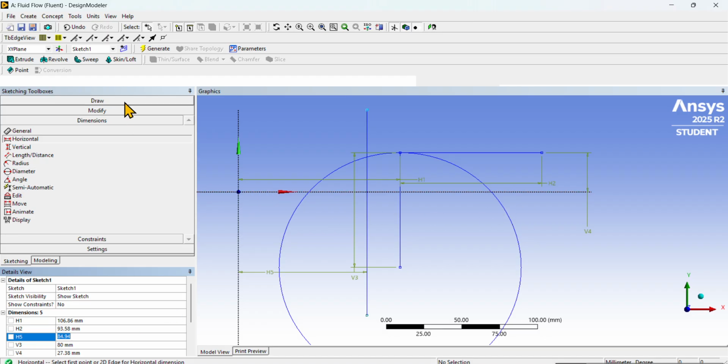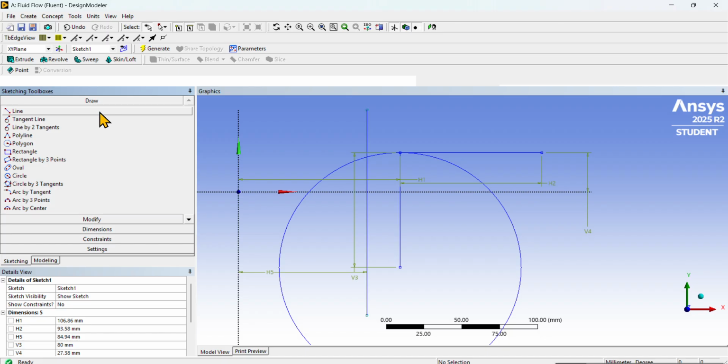So now we're going to take a line. Okay, so I will try to draw a line. First I will try to see: this is the edge selection, this is the point selection. I will deselect edge because I need to select only points here. So I will go to line. I will select only the point at the center of my XY lines.